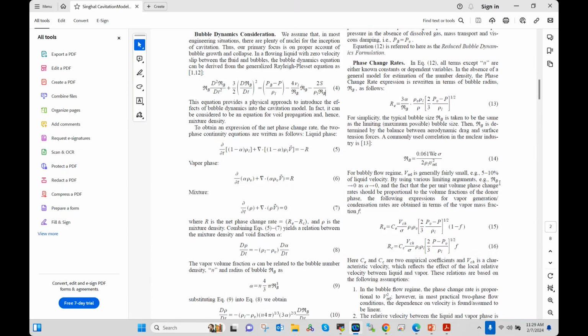I think we have 4 or 5 different variables that help us look at cavitation in more detail. So 0.5 is a number that we used, which means that it's very clear that there is cavitation happening. But if you use a lower number, that could mean that it's just the early start of the cavitation. So this is something that we cannot say for certainty. It's something based on looking at probably 2 or 3 different parameters together. We can make this judgment about which number is the best value to use.